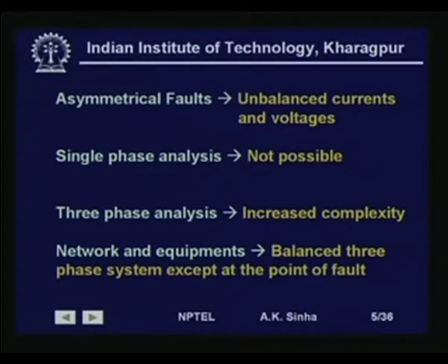Now we will talk about asymmetrical faults. As we have said, asymmetrical faults create unbalanced currents and voltages in the system. That is, the three-phase symmetry of current and voltages are no longer maintained. Therefore, the single phase analysis which we could do can no longer be used in this case.